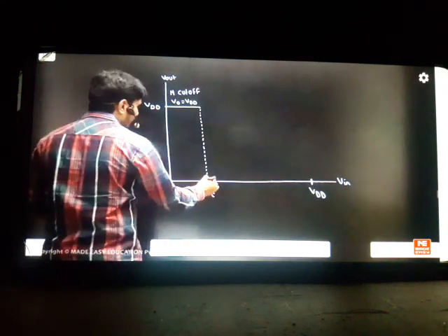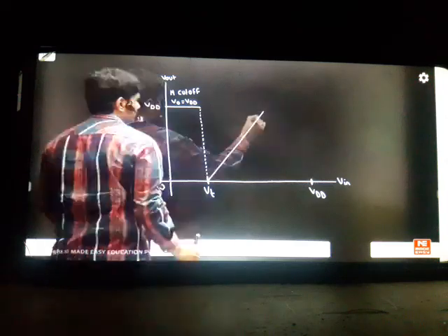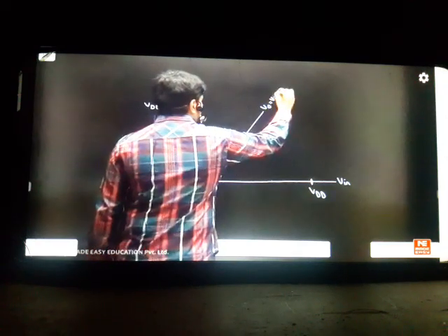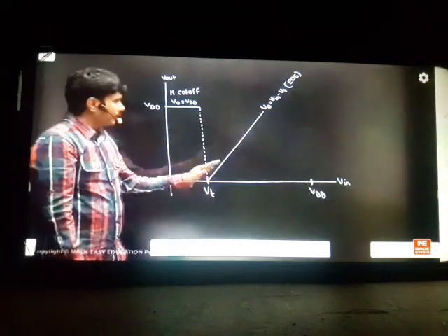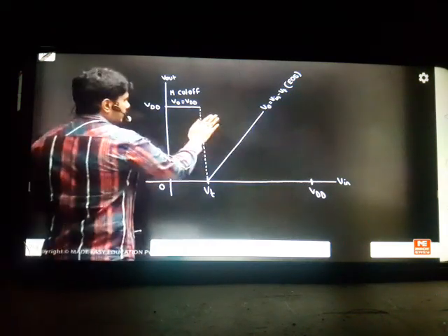After that, we have one more line, a boundary line we can say. Some line like this. This boundary line is V0 equal to VIN minus VT. This boundary line we call the EYS line, edge of saturation line, in step 3 we have created. What this boundary line tells is: above this is current saturation, below this is triode.